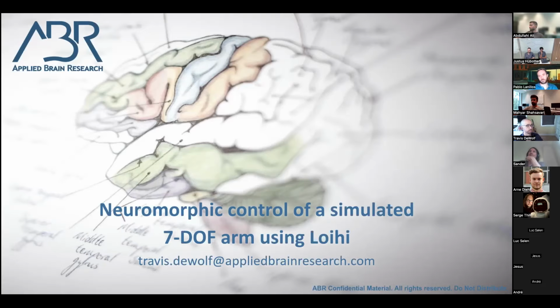The second stage then was taking each of the nodes with a specific set of functionality and implementing that in rate neurons. Afterwards, we do that same thing with spiking neurons, and then finally we take our network that's now fully spiking and we adapt it based on the constraints of the specific hardware that we want to implement it on. And this will involve taking into account a bunch of things, like usually memory constraints in terms of the bit width of the weights or the connectivity that can be allowed between different layers, all of these kinds of things. And this whole process is really iterative.